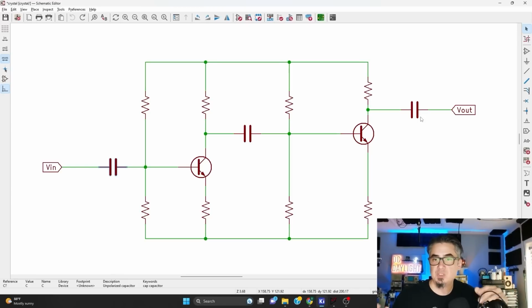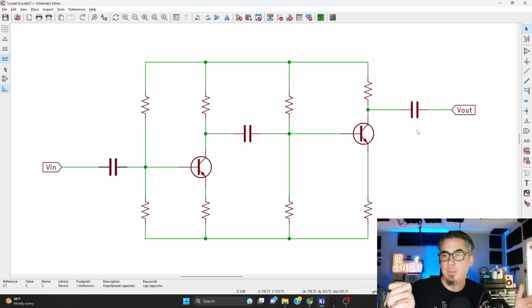If we're feeding something else, we want to make sure that we're not setting our collector emitter voltage to the next thing that we're connecting it to, like a guitar pedal. We don't want to feed a DC voltage into the amp, though it should be protected already. We want to make sure that we take care of it on our side. Okay. Now this is of course effective at audio frequencies as well as radio frequencies. So I have an application on the bench over here. It's a UHF 100 watt amplifier, and it uses this technique to isolate stages between the preamp and the output stage. So let's take a look at that.